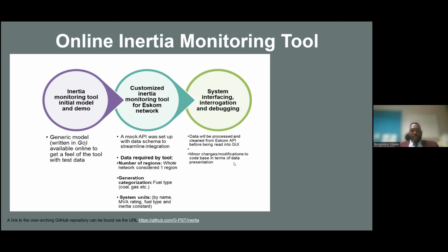So obviously from the studies, we know how to filter out some events that cause errors. Some units like PDC can cause errors, small disturbances can cause errors, and the incidences where IDR, instantaneous demand response, operated, we need to filter out. So those are the things that we're going to do.